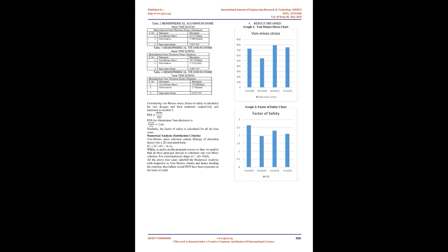To validate any design, it must satisfy a minimum FOS of 2.5. Equivalent stress is found to be 126.13 MPa, which gives an FOS of 1.982, which cannot be validated. Hence multiple iterations are carried out to meet the safety factor of 2.5. Modeling and analysis are repeated for the new iterated thickness. The respective values are stated in tables.